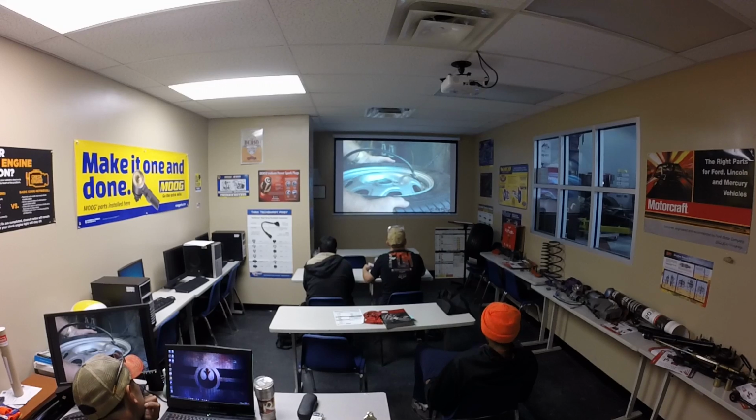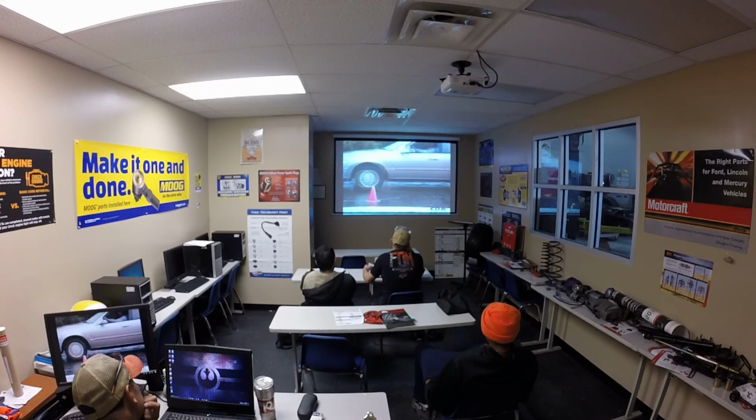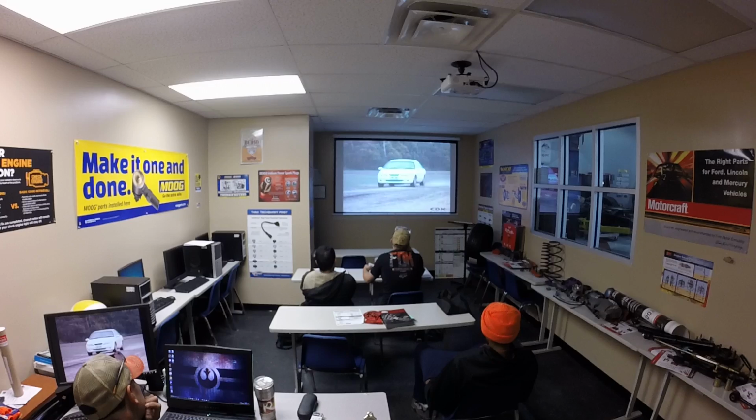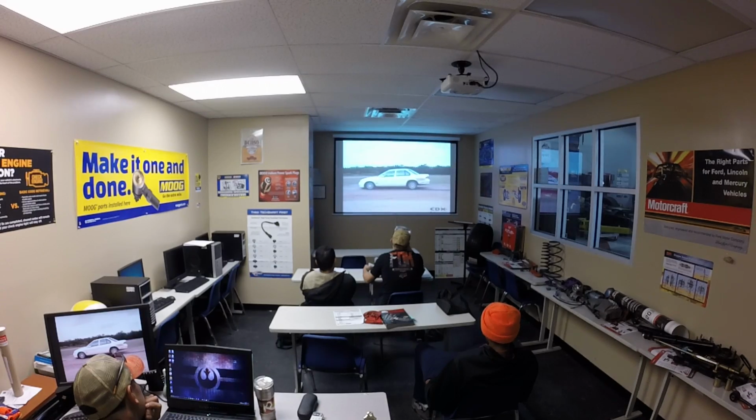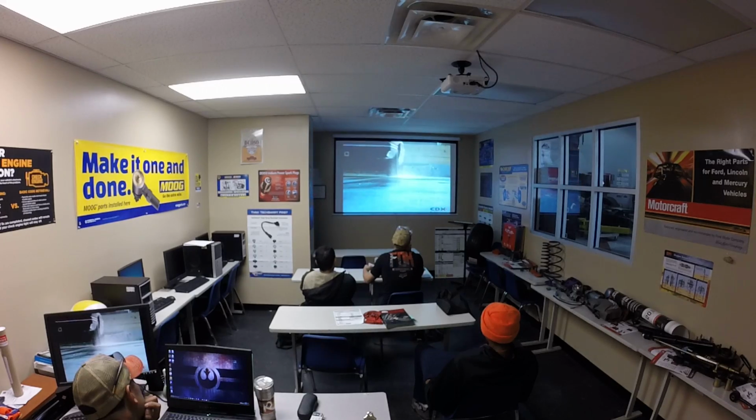The tire must be an exact fit on the rim to fulfill a number of functions. It ensures that the narrow contact area between the beads of the tire and the rim will seal the air in a tubeless tire. It transfers all the forces between the tire and the wheel without slipping or chafing. It ensures the friction between the tire and the rim prevents the tire from turning on the rim.